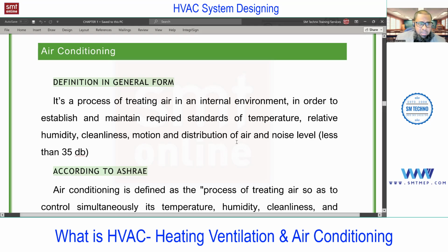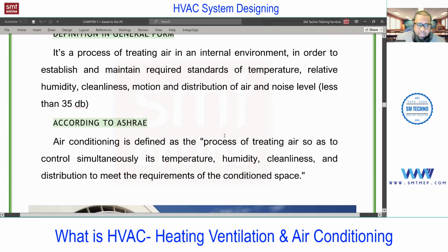So this is about air conditioning in general terms. But now if you talk about air conditioning as per ASHRAE, this may again be asked in an interview. Air conditioning is defined as a process of treating air so as to control simultaneously its temperature, humidity, cleanliness, and distribution to meet the requirement of the conditioned space. Or in other words, as per ASHRAE, it's a condition of air in which the human mind should feel comfort, and the body will feel comfort when you maintain all these parameters. So this is about HVAC. I think you got the idea.